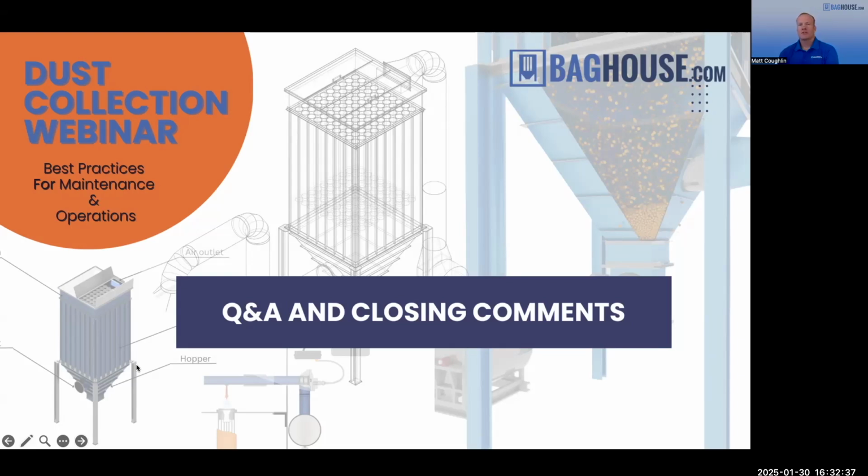Well, the semi-answer I usually give is that a rough middle of the road estimate of about a year is fairly reasonable, but of course it depends. So the fully lawyerly answer is that it depends, right? Like I said earlier, if you're running it hard, a lot of heavy dust loading, 24/7 operation, abrasive dust, temperature spikes, all the worst things you can think of. If you're throwing the whole kitchen sink at it, you might have to change your filters every 2 weeks or every month. It really just depends.